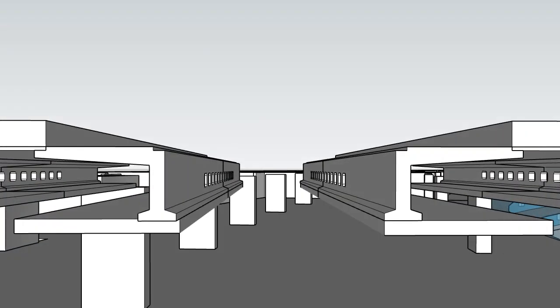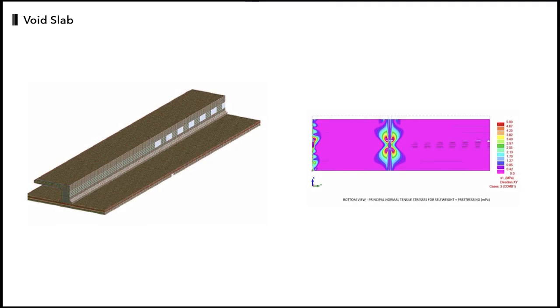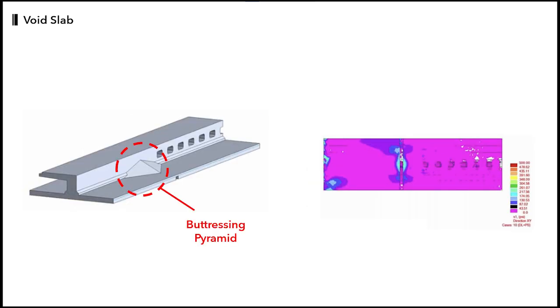The internal structure of the slab is as follows. The metal deck connecting the upper part of the precast is raised, and as the space underneath is hollowed out, a hollow layer is naturally created, and a concrete diaphragm is poured on top of the metal deck. However, with this shape, there was a problem with strong stresses in the red area, as shown in the following image. To solve this problem, a pyramid-shaped haunch was installed, and the final shape of the hollow slab was created.